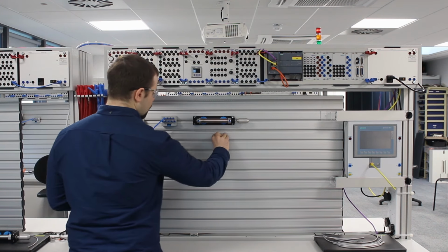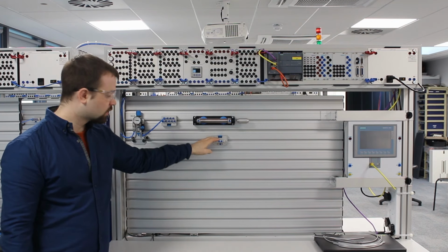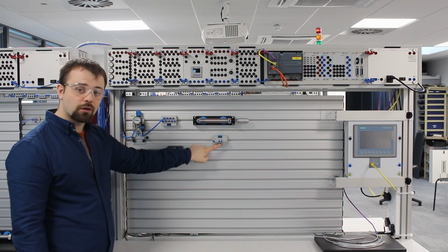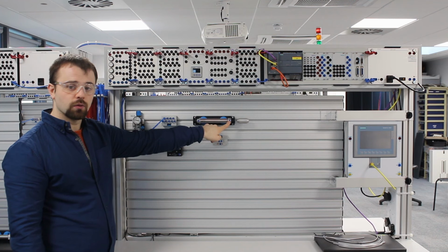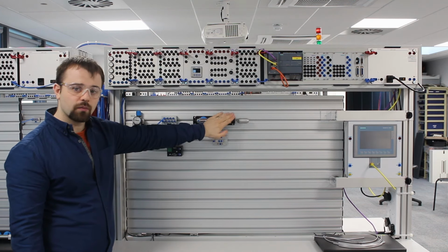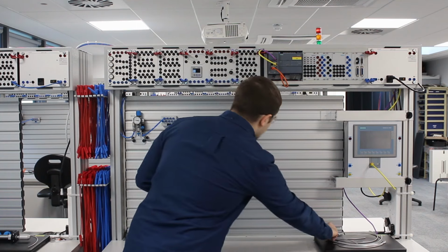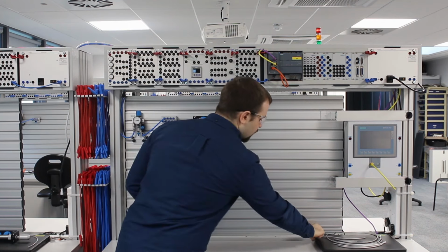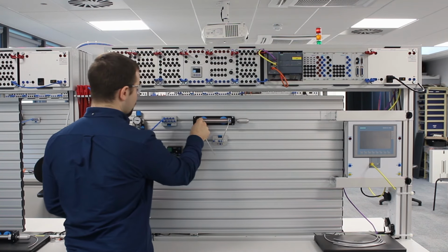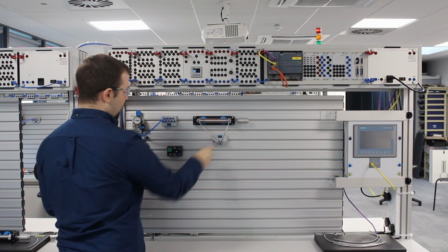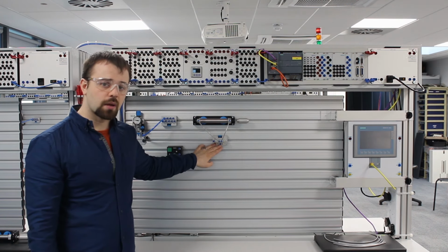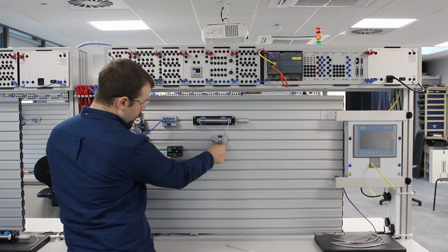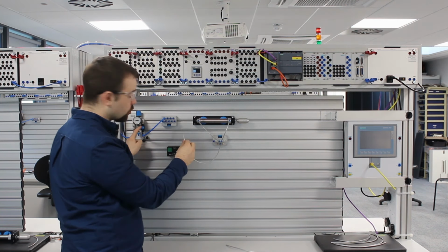So I'm going to place it directly below, like this. And we have 2 over this side and 4 over this side. We remember that when we power it with 1, air normally goes from 2. So I'm going to make 2 go to this end of the cylinder, so that it retracts back by default. So we go from 2 into there, and slightly different pipe, from 4 into the back. This means if we power it by default, remember, it's going to stay exactly where it is. I'm going to take a pipe from 1 to my manifold, making sure my manifold is off.